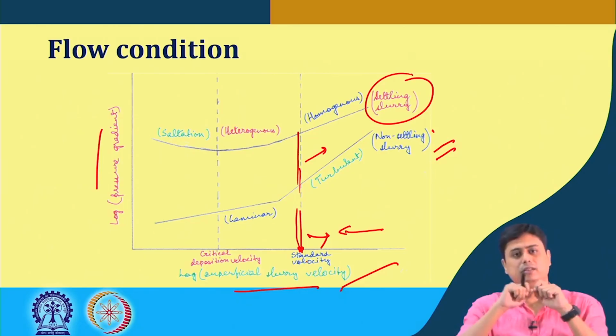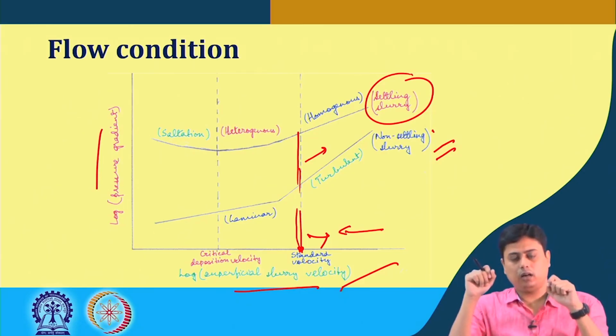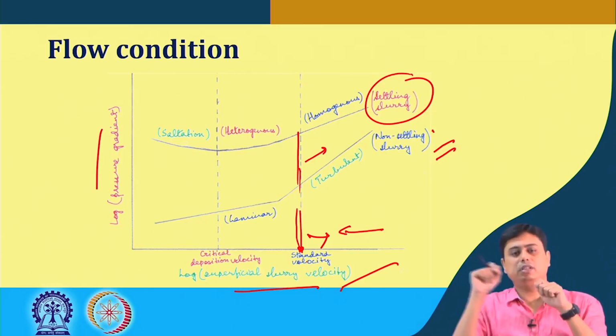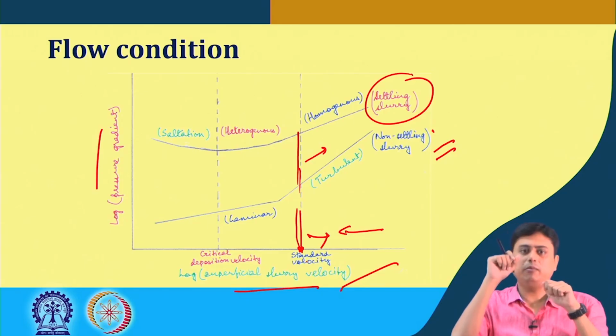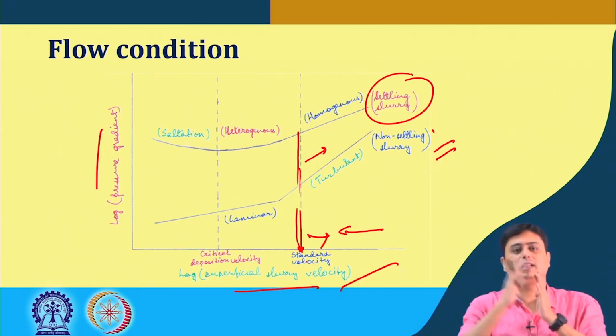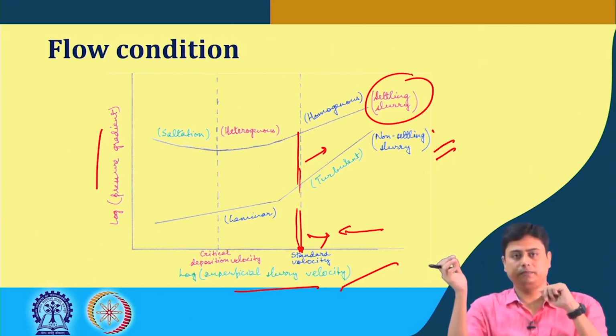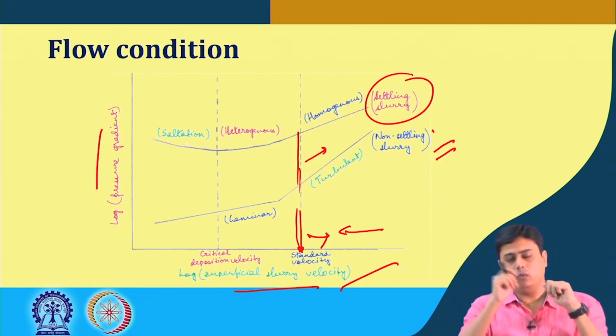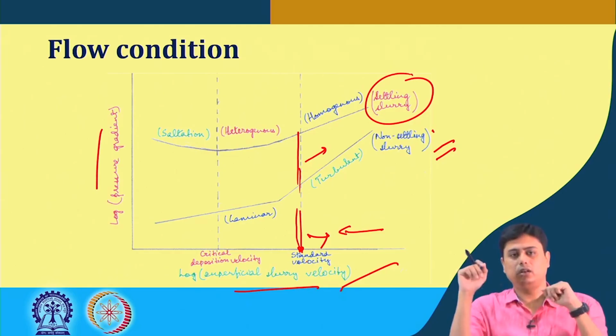The point is the relative concept of the time it takes to settle and the distance it travels within that time. If it reaches a certain distance within that time, it can remain suspended for a longer time, and that happens here. Once we increase the bulk velocity to a greater extent, then in the settling time in which it was falling, it would travel a long distance.